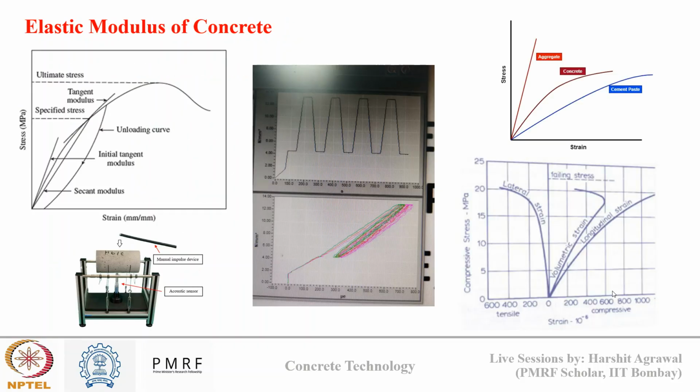the concepts. So last week we concluded the ninth week of the course, where we continued our discussion on mechanical properties of concrete by discussing the modulus of elasticity of concrete. In modulus of elasticity, we discussed what is MOE, and why concrete shows non-linear inelastic behavior in the stress-strain relationship. We talked about different MOEs of concrete, different ways to measure MOE, that is using the static method and the dynamic method, different types of MOE based on the direction of deformation, and finally how concrete properties can affect the MOE value.